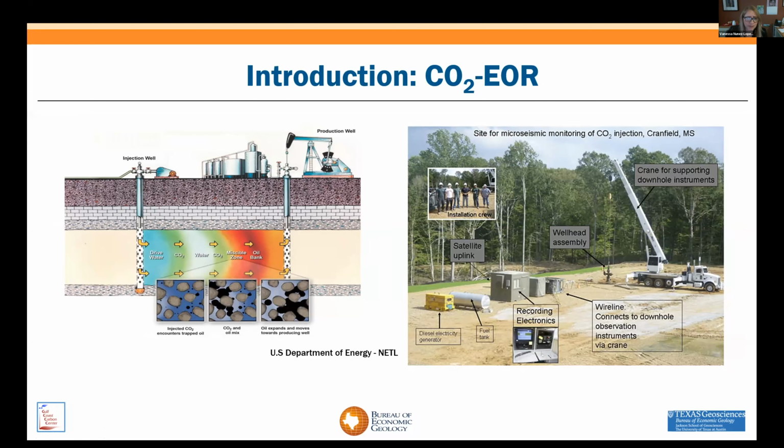And in the Permian Basin, it is very common to also process the produced gas, which is a mix of the CO2 and reservoir gases, so that CO2 is compressed and re-injected pure, or almost pure. In some cases, the operator might decide not to separate the gases, and so all that gas stream will be re-injected. That has pros and cons economically and performance-wise.